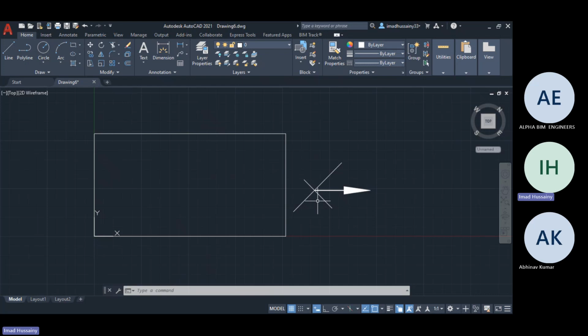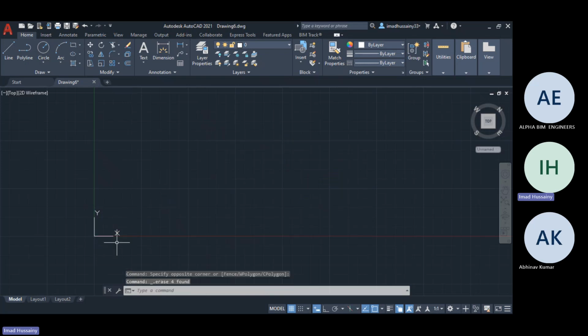As of now, I have made it 45 degrees. If they ask you to match, then if your drawing is 45-degree deflected, bring it back to 45 degrees, work on it, then send it back again to wherever it is. So we should know what is the world coordinate system and what is the user coordinate system. As of now, don't go drawing everything like that. I'm deleting everything. Don't get confused.